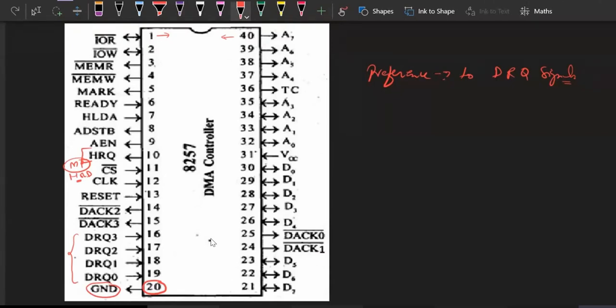Once the microprocessor has released control of the different buses, it will send HLDA. HLDA is an output signal of the microprocessor, but an input signal to the DMA controller. Once HLDA has been received by the DMA controller, it can control the data, address, and control buses of the microprocessor, and it can now either read or write.